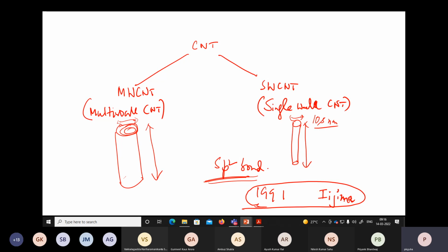Carbon nanotube can be used as a via, as a connector, like I talked about. At the beginning, I talked about how in CMOS there are multiple metal layers, and the multiple metal layers are connected through vias. Those vias can be made of carbon nanotube, because it can have a very large aspect ratio, very tall. As I said, the length is as long as 1 micrometer or so, and the diameter may be a few tens of nanometers, even less than tens of nanometers.